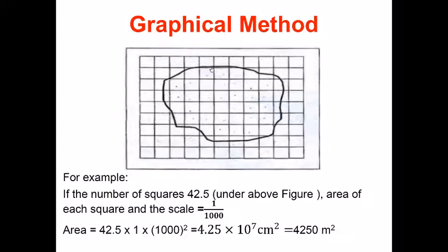First you count the number of boxes which are completely inside, and then you can compute the area of these partial boxes, and that's a rough procedure. So if I see this box, I can say that it has been covered inside the traverse, let's say 20% of it or 25% of it, and this seems to be 40%. So this would be 0.4 plus 0.25 plus whatever we have over here, and that would be partial areas of the boxes covered by the traverse.